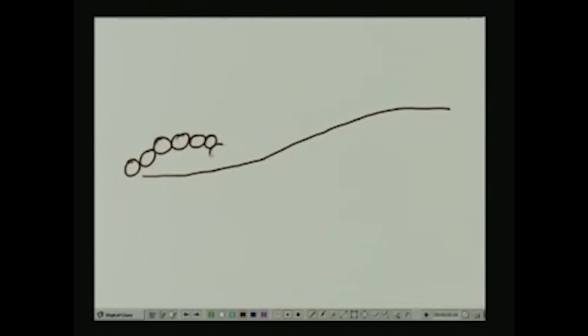So here we are looking at a few cross sections. So basically, boulder pitched seawall is a trapezoidal wall constructed a little bit offshore, and they have got heavy boulders at the surface and a little bit finer ones within the core areas. So this is the typical details of a rubble mound.